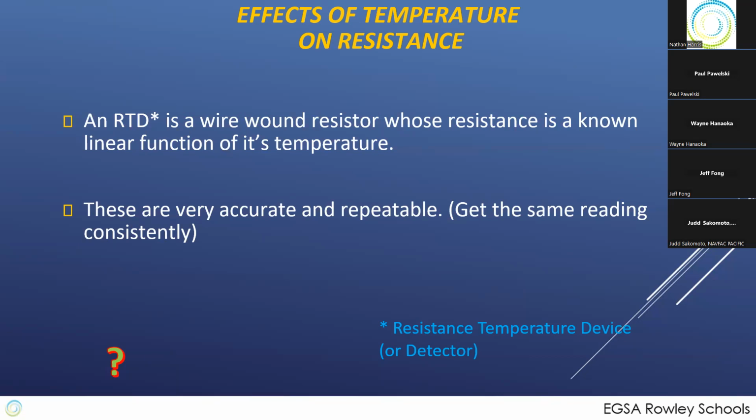These are basically a very precise thickness and length of copper wire with some insulation around it, jammed into the windings of the generator or any place else you're trying to measure temperature. And it's a separate circuit because the insulation blocks it from the rest of the coil.